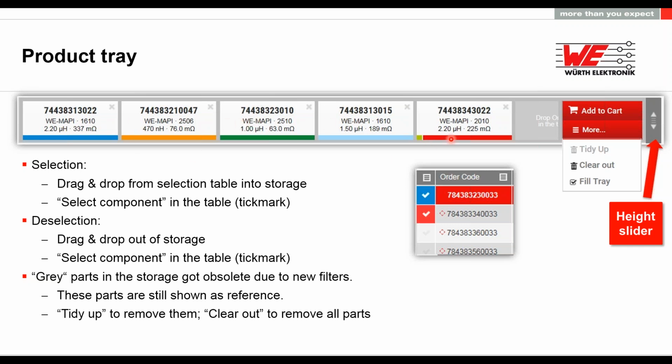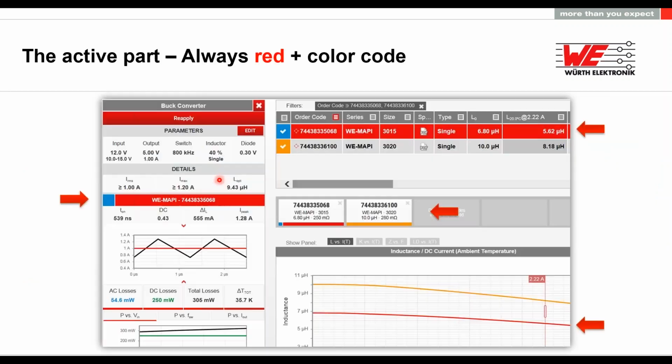For example, you have selected 5 components by integrating 2 or 3 filters. When you add one more filter, and if one of these components doesn't fall under your filter, the component will go gray. The black text here, the part number, will become gray. This means after the recent addition of the filter, this component has become void, or it is deselected.